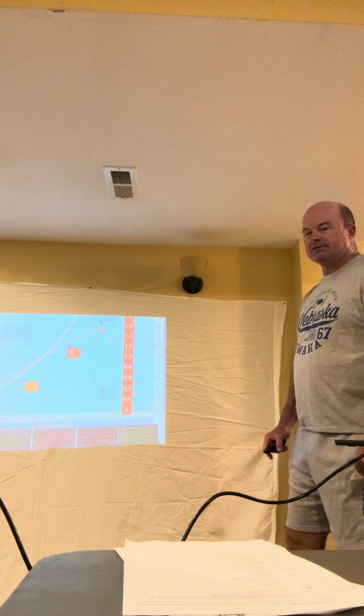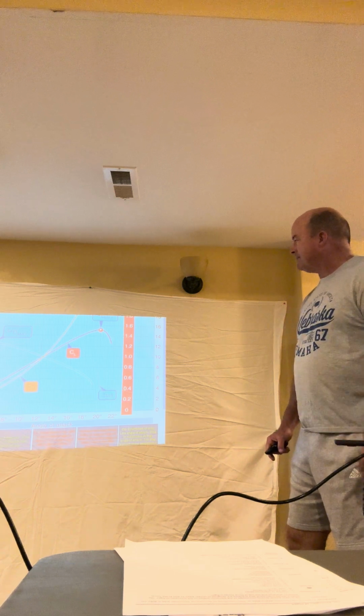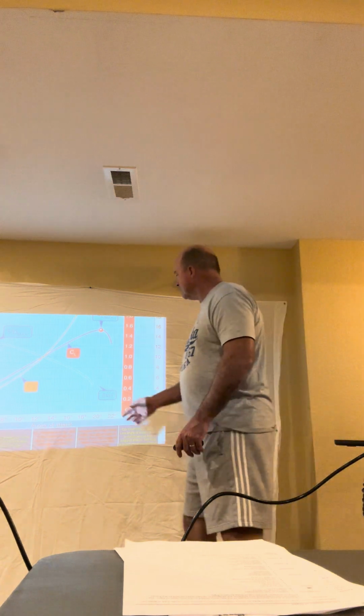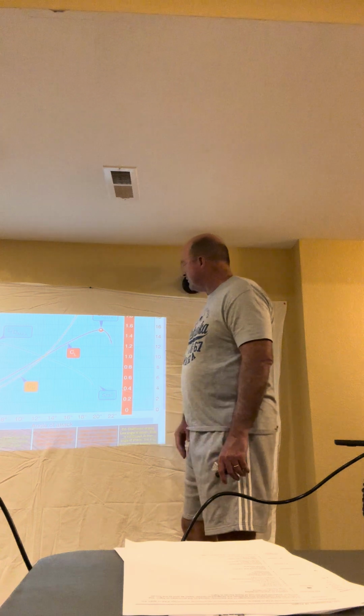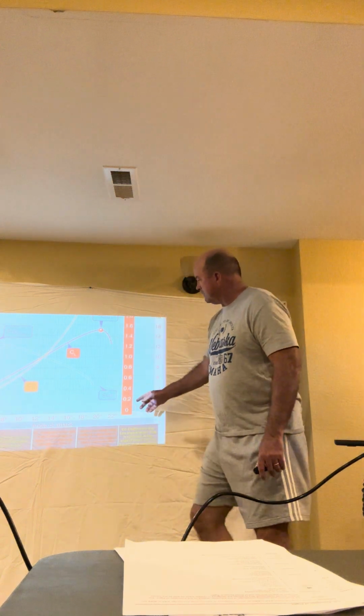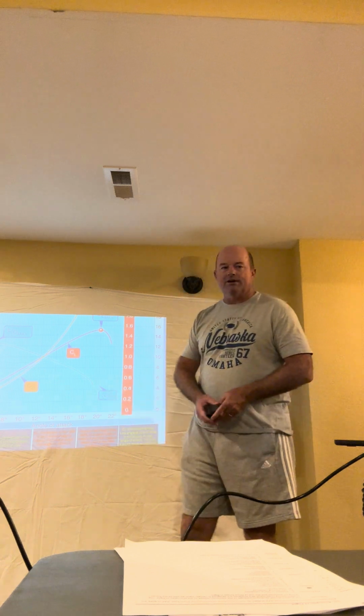So this is a great graph that you really need to understand, because it will help you understand why the airplane flies. And of course, you've got the two stall areas right here, at the 20%, and that's where they're going to stall. We'll talk about this in another video, but always remember that an airplane will stall at the same angle of attack, regardless of weight. So it's always right about this 20%, and you can see that with stall here and stall here. So anyway, pretty cool stuff.